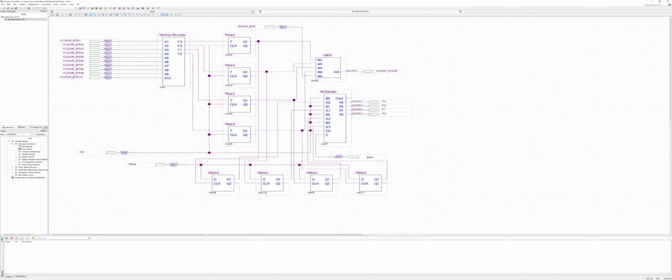Here are all the floor buttons, the encoders, the T and D flip-flops, the BCD adder, and the door state, all the outputs. And so the circuit goes from left to right. It starts off with a 10 to 4 selector, which is for each floor. Only one of these can be active at any time. There are 4 outputs, so it produces the binary information of the selected logic high signals.